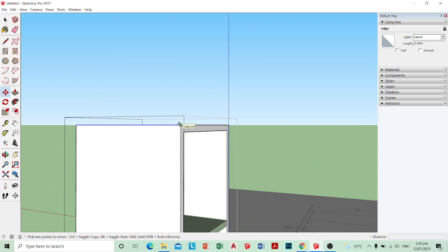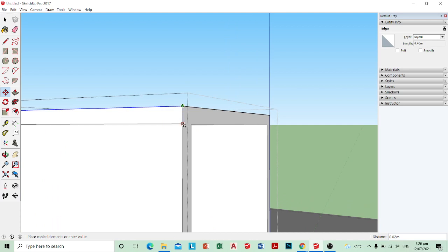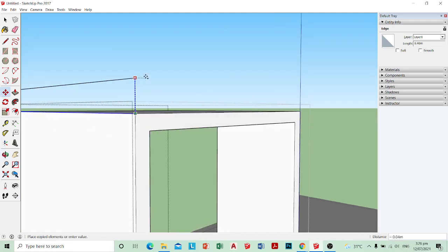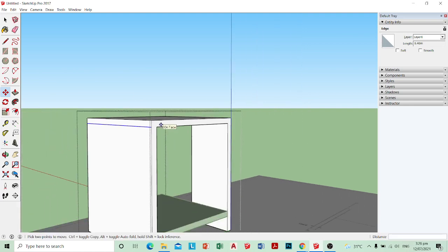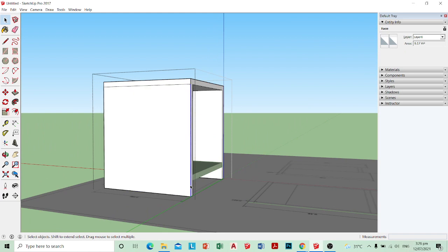So move, control, and then move your mouse up and down to the point where you want your line to go. Another tip here: if you press up, it limits the movement of this line to only the vertical axis, the blue axis. To make sure that's aligned there, I'll move this line over here, control and then plus to move this line down here to the left.